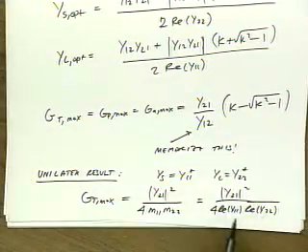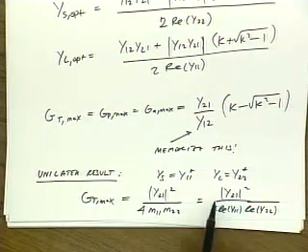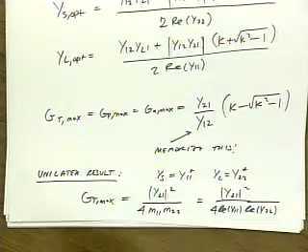So that long calculation we did to get the power gain of a MOSFET, we could just directly plug into this equation. y21 is gm, the real part of y22 is just 1/RO, and the real part of y11 is basically just a series to parallel transformation. Questions or comments?